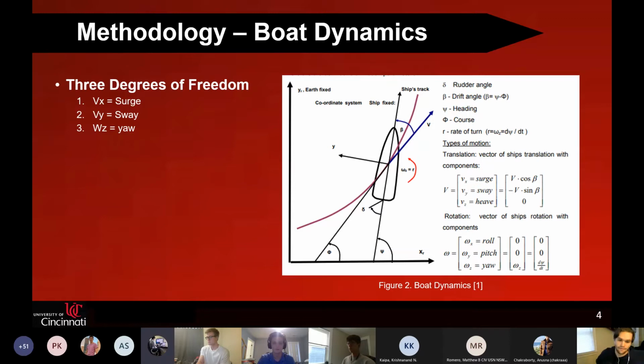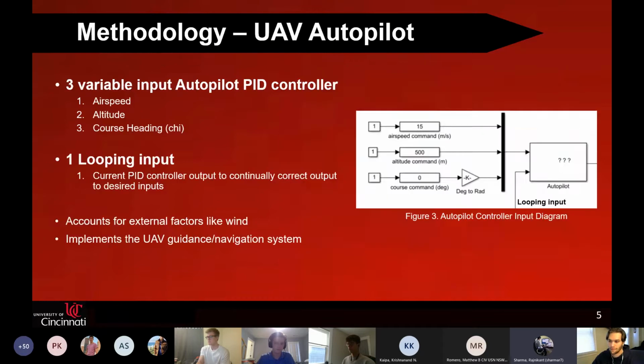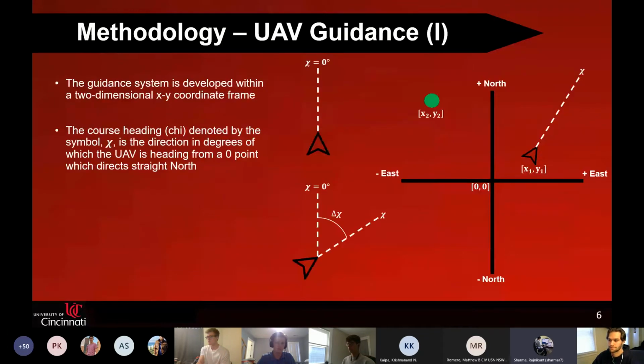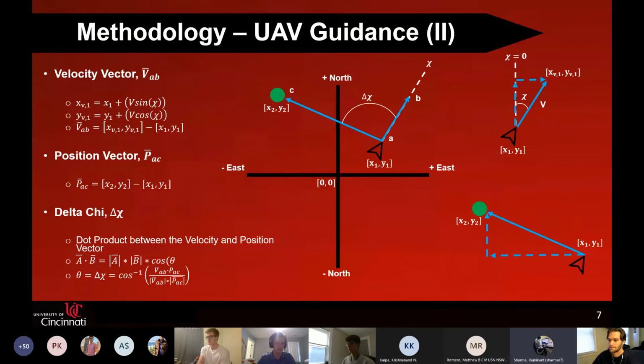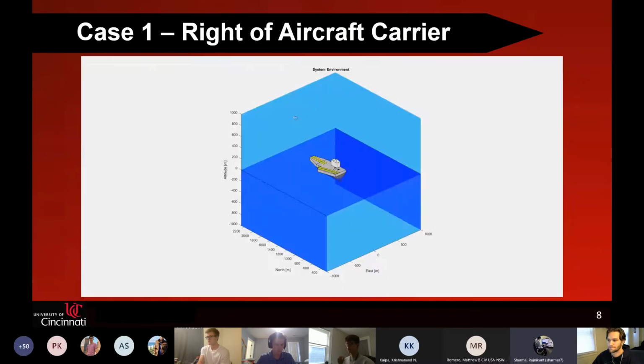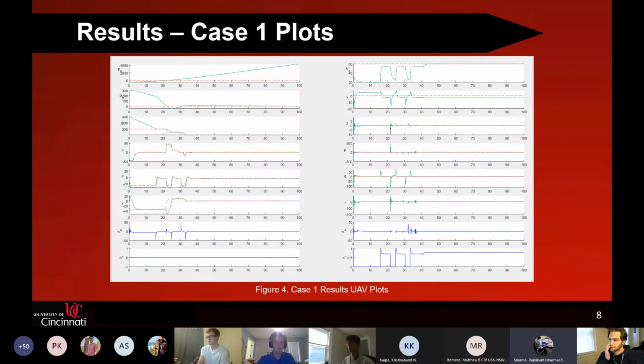I have one question. One is orienting. Did you also consider velocity, or how fast the aircraft should change the altitude? Did you check those constraints and put any constraints on that? Yeah, the guidance system outputs a velocity also to input into the autopilot, and you can see that whenever it slows down to change height, the velocity does slow down, and then it begins to speed back up again to match whatever it needs to catch up to the ship.